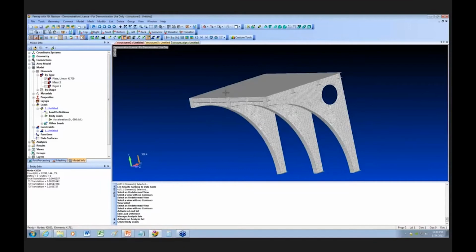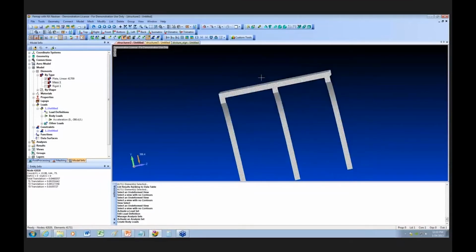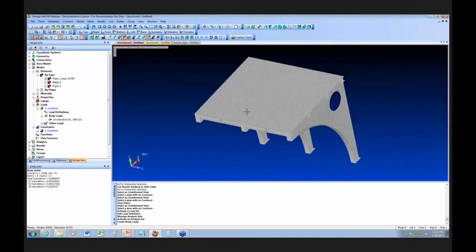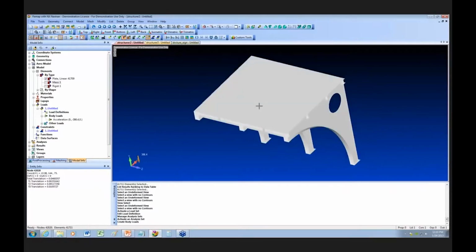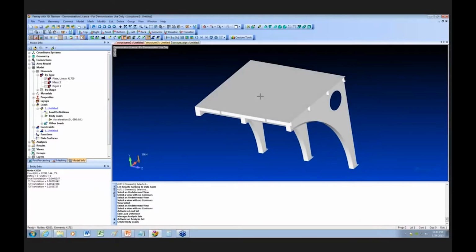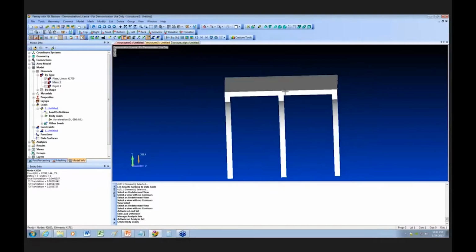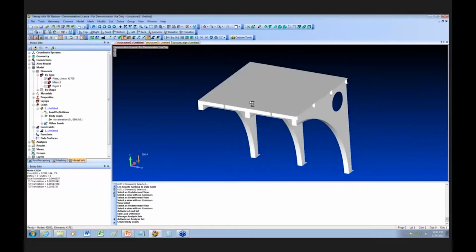And so we can see I have this modeled all with plate elements. And what I'm going to do, when I put stresses on here, it kind of gets showing the grids. It kind of covers things up. So I'm going to click that so we can turn those grids off. And so I'm going to put a mass on here. I'm going to drop a mass. So there's my mass. I've just turned my mass on. It's sitting up here.